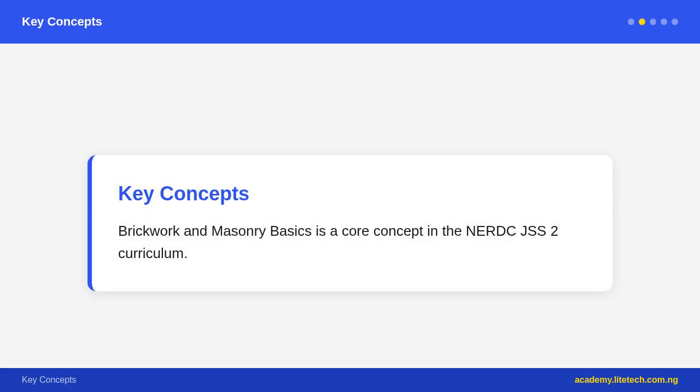from available materials. Standard sandcrete block sizes in Nigeria include 9-inch blocks, approximately 450 mm x 230 mm x 225 mm, for load-bearing walls, and 6-inch blocks, 450 mm x 150 mm x 225 mm, for partition walls that do not carry structural loads. Mortar is the adhesive mixture used to bind bricks or blocks together.